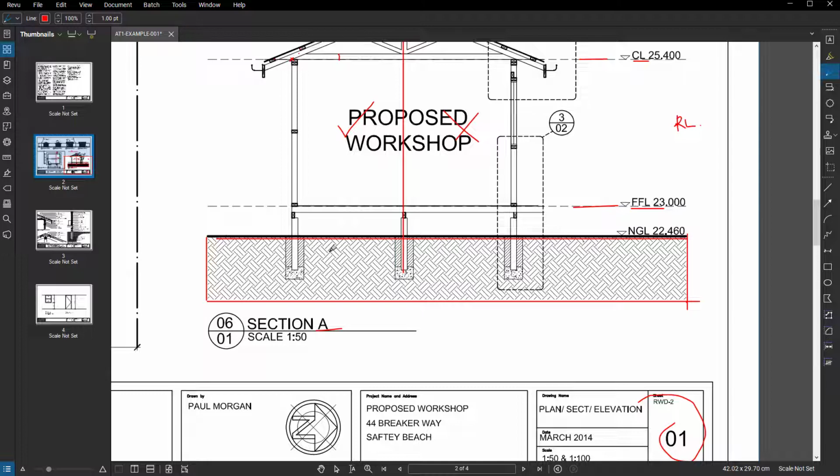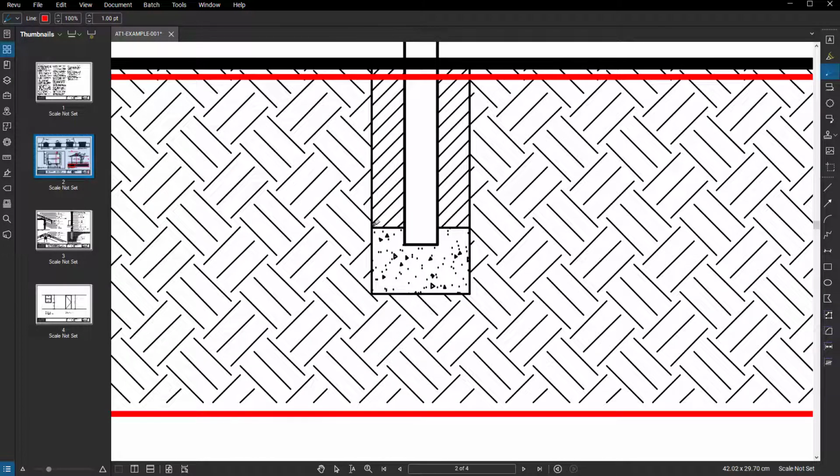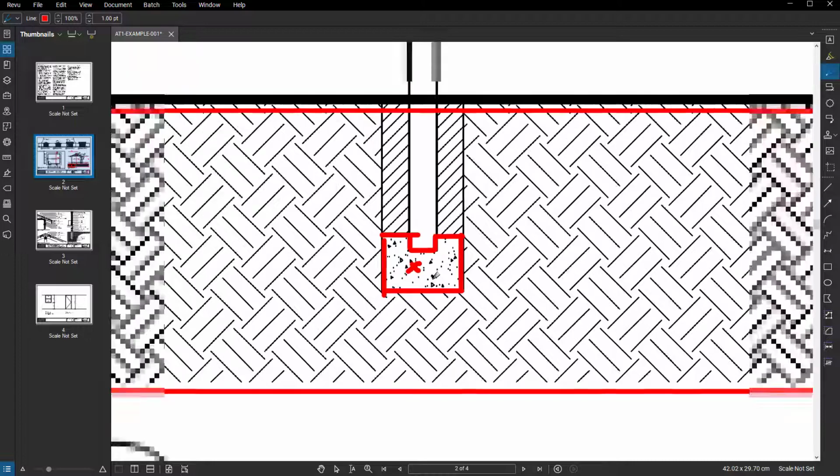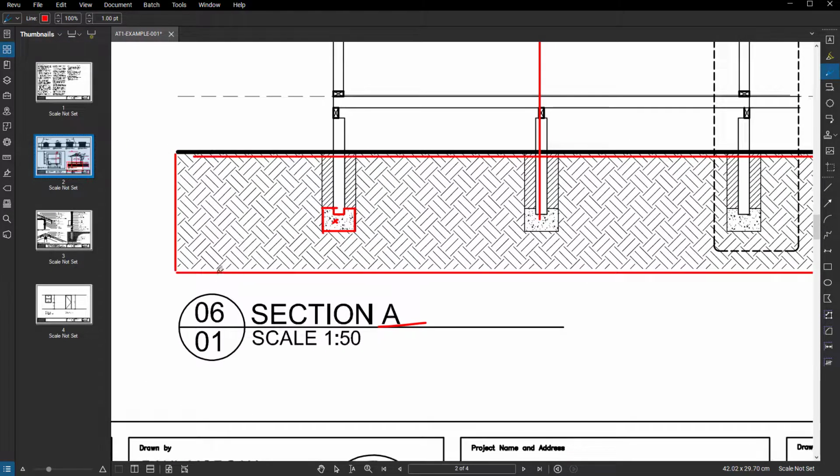Okay. Now the way hatching works is hatches in AutoCAD are basically patterns. That's all they are. And they work by finding the boundary of lines and putting a pattern within that boundary. That's why when you use the hatch command, it's looking for these lines here, because it then fills up anything within that space provided my mouse is hovering over this area. And likewise for these areas here and the earth hatch. That's why we have to draw this boundary here, because otherwise AutoCAD wouldn't know where to stop hatching.